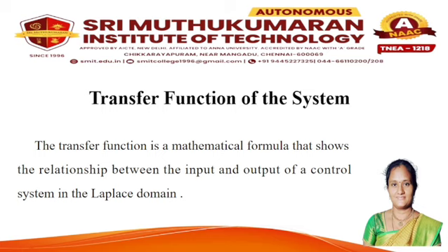Then we are going to see the transfer function of the system. How to determine the transfer function of the system. Transfer function is a mathematical representation that shows the relationship between input and output of the system in the Laplace domain. For example, input denoted as R(S), output denoted as C(S), we have to find the transfer function of the system T(S) equal to C(S) divided by R(S). It is useful for system analysis, stability study, and control system design.